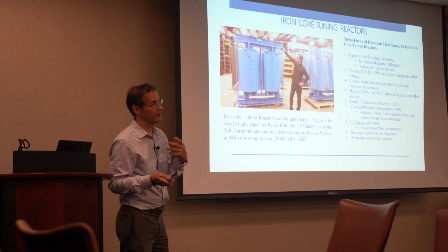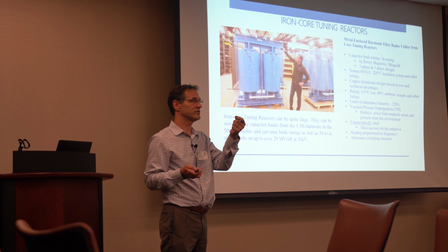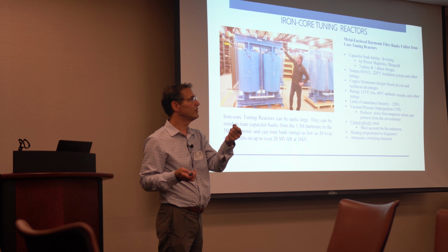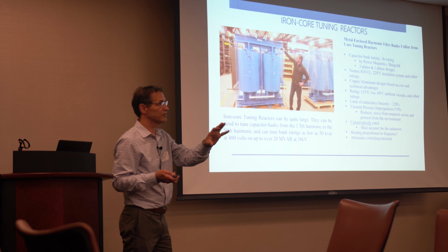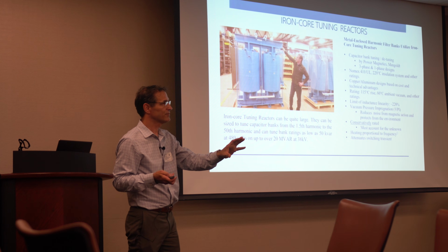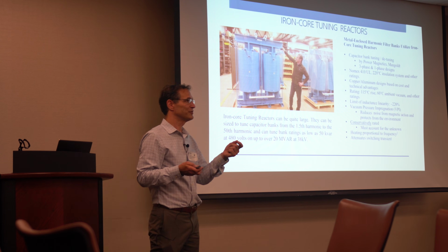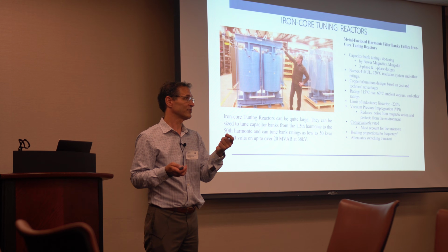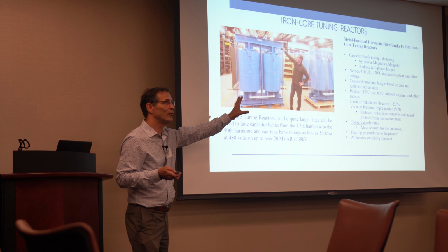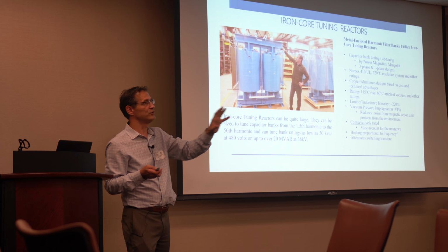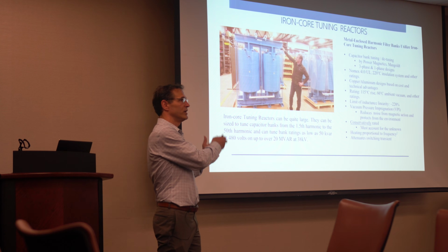So what I mean by 50%, it means that a fifth harmonic, I would rate at 50% of the fundamental or 100% of the fundamental. The reason we do that is even if the study only shows 10 or 20 amps, I'm still going to want 100 amps, because the study doesn't always come out to be exactly what you get. You might have not been told about some large drive. In the future, the customer might add a large drive, so you want to add rating in the reactor.